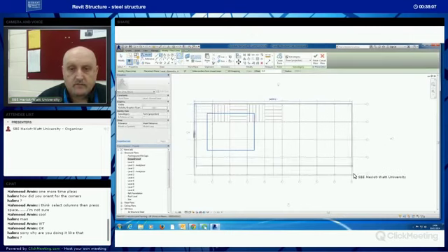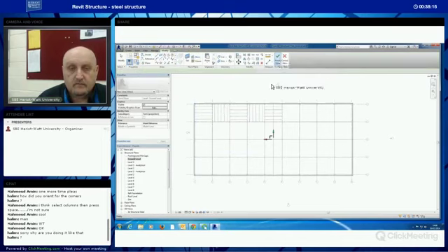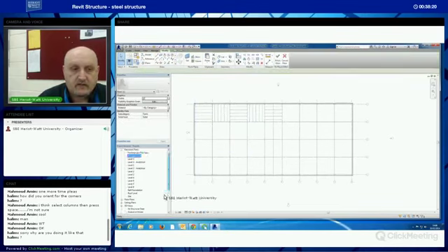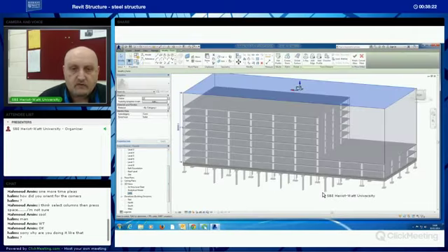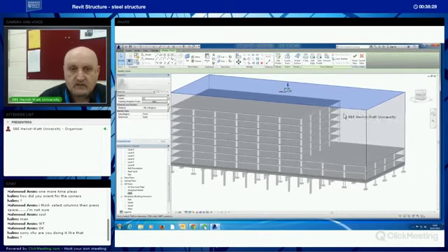corner to corner. And the bit that people forget, and I would like you not to forget this, is this bit here. I'd like to create the form. We don't actually have to finish the mass just yet. I want you to have a wee look at this in 3D. You'll see we've got this rather odd 3D shape, translucent. You wonder what that could possibly have to do with the building. Well, it's because we can use that to place things on top of its surfaces. And in my case, it's going to be glass walls. So I'm going to move this one down. Whoops.